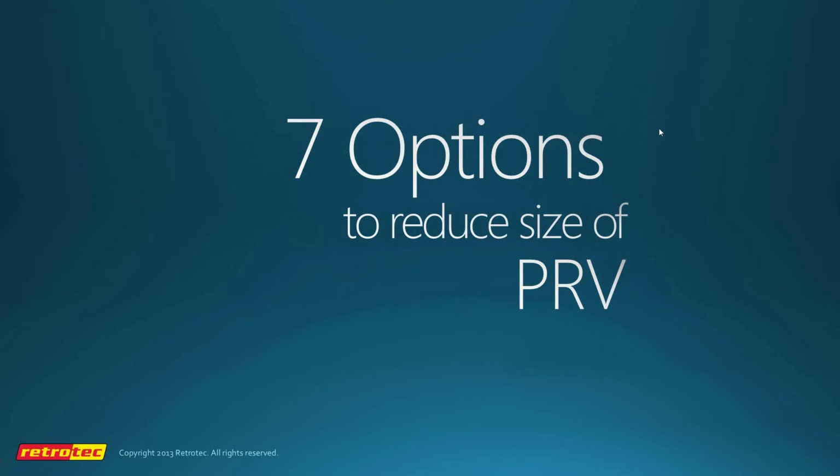So this section here, 7 options to reduce the size of the PRV. For the NFPA folks, these 7 options can be utilized to eliminate the need of a PRV altogether. Again, bear in mind the ISO philosophy, or the European philosophy, is you always need a PRV. You can never rely on enclosure leaks because they think somehow they will disappear. I've never seen that happen, but that's their engineering choice. And the NFPA folks have a slightly different philosophy, that their enclosure leaks probably will do nothing but get bigger, so we can rely on them for venting.